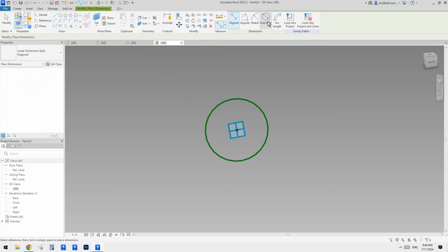Okay, so now final. Can we add something like that? Yes, so let's go back here, edit family. What we can do is type HH, just temporarily hide the model. So we can just place a point, use draw on face. Sometimes we need to rotate a little bit in order to place onto this line. Otherwise, for some reason, it's not picking the lines, so you just need to rotate a little bit until,